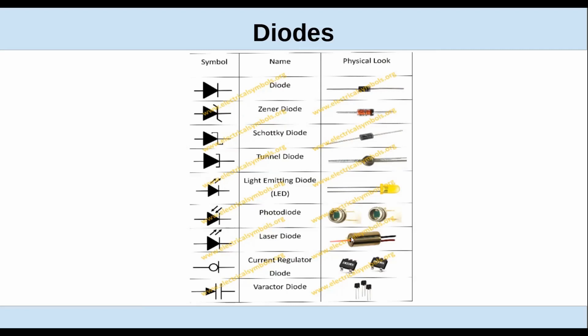Laser diodes are used in a lot of things nowadays. The small ones like in the picture are usually about 5 milliwatts, and they can either be set to generate just a single dot, or with a little lens on there, they'll generate a line. So you can use them, particularly in a laser cutter with a couple of those on there with a cross. On milling machines and other things, you can use them for alignment.